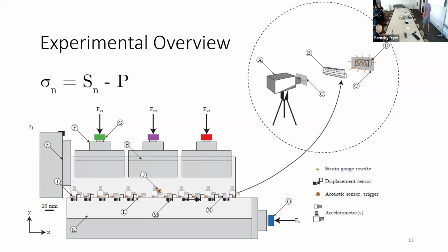We also have, Francois has a very high-speed camera. And this high-speed camera basically is light that's emitted from these very bright light sources. It goes through a polarizer. It then goes through the PMMA samples. And depending basically on the stresses in the PMMA, this light is basically diffracted. And once it comes out, it's then picked up by the camera. And depending on this diffraction, you can then see where the stress intensity is for elastic material. In this way, you can track the rupture front.